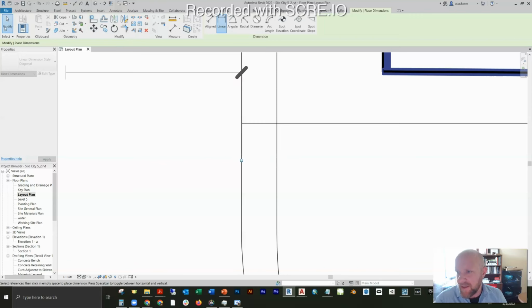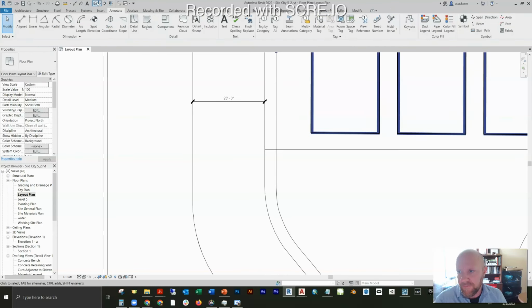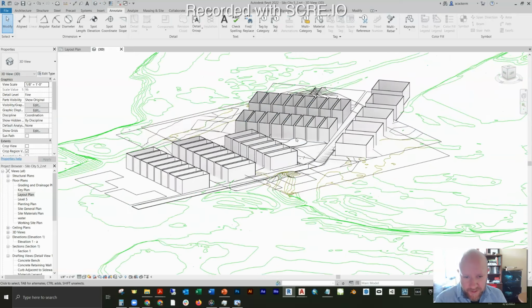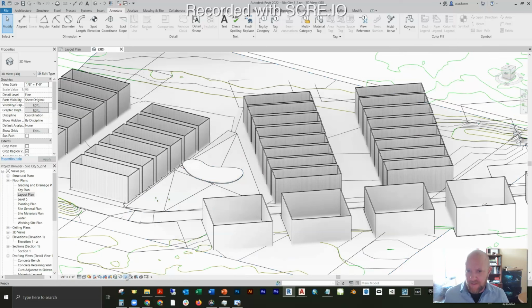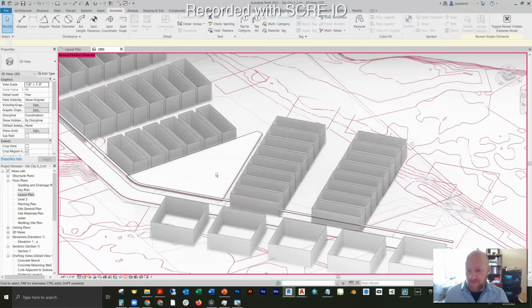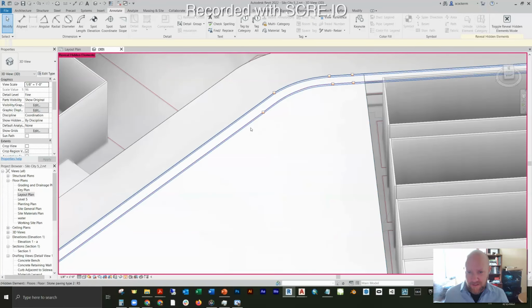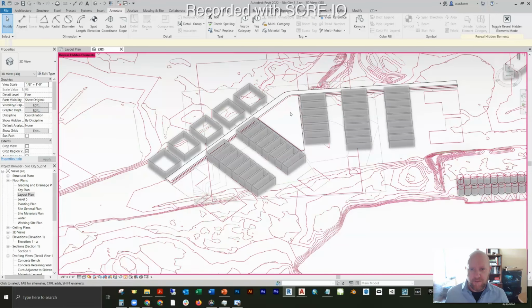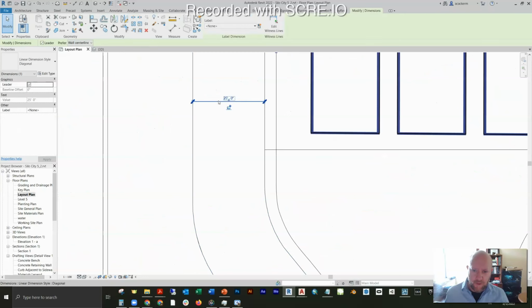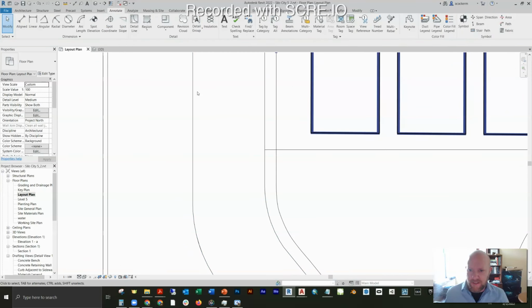If it's not, it might be because I've got a couple floors floating. You can see here I've got a couple floating floors. Actually, one's hidden in this view. So this might be a source of your problem also: I've got a couple different elements floating above each other just for visibility in my materials plan. But you can work that out with some troubleshooting. More or less, there's always a reason why your dimension isn't attaching.